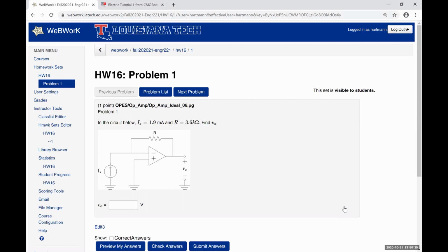What's the voltage drop over that resistor? You don't need to give me a numerical value, just tell me how I'd figure it out. Right, so the current flowing from this source, all of it is going to flow through that resistor because none of it can branch off.